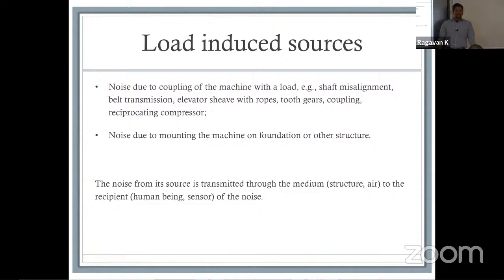It can be a function of wearing out of your bearings. So your bolts, the bolts that you have attached. In some cases, it might just be as simple as the motion or the vibration in the overall body was substantial enough that your bolts were not accurately sized. The diameter of the bolt has to be right to make sure you don't end up causing them to wear out sooner than normal, right?